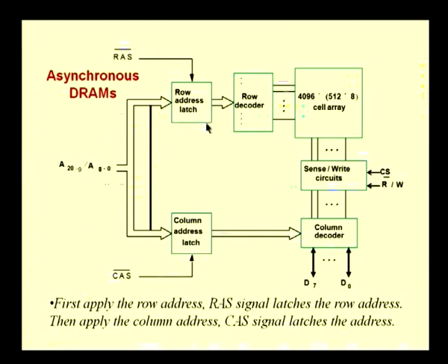So, which is why you will find that we have something called a row address latch over here and a column address latch over here. I will first send the row address, and when I send the row address, I send a signal called the RAS signal, or the row address select signal. Okay. So, you first apply the row address and send this RAS signal along with it. This is an indication that what is coming in is a row address, and so this RAS signal will be the one that enables this row address latch. When the row address latch is enabled, whatever address is coming here will be stored in this row address latch. So, we have got the row address in this latch, and this address now will go to the decoder. This decoder will select one of the rows that we want.